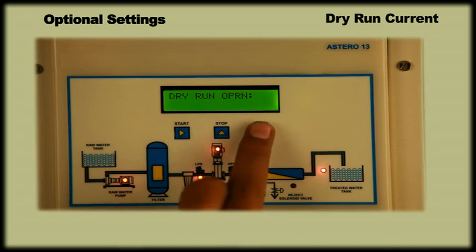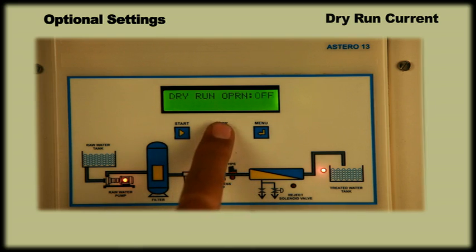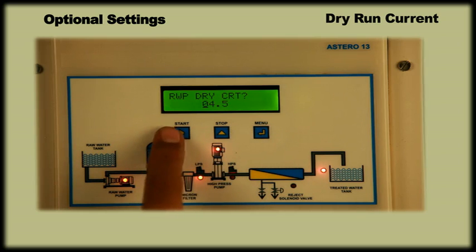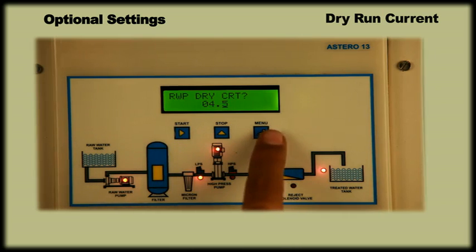The display will show dry run operation. On pressing the Menu key again, the display will show dry run operation off by default. In order to turn it on, use the Stop key and press Menu. Now the display will ask for the raw water pump dry current value. This set point has to be between normal current and dry running current. For example, if the dry running current is 3 ampere and normal current is 6 ampere, then one can set it to 4.5 ampere and press Menu to save. Similarly, the high pressure pump dry run current value can be set. Press the Menu key to save.